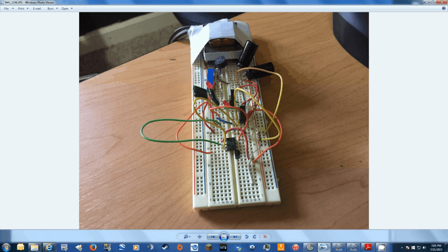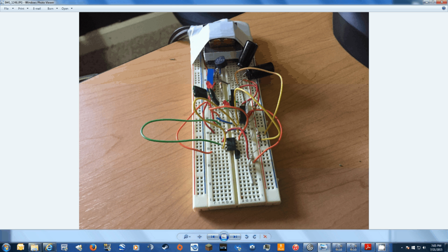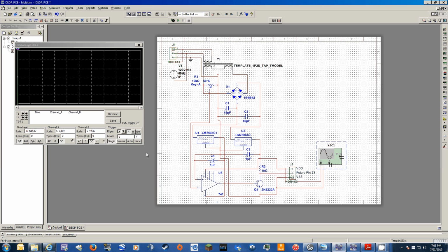This was our original test circuit. We built this on breadboard, obviously, and this is pretty straightforward. Here I'll bring up the Multisim design that we used for testing. 120 volt RMS, feeding a transformer, so a rectifier. Same basic circuit that we saw on the breadboard. I'll simulate this now, and we can see what happens. So we get a decent step function.